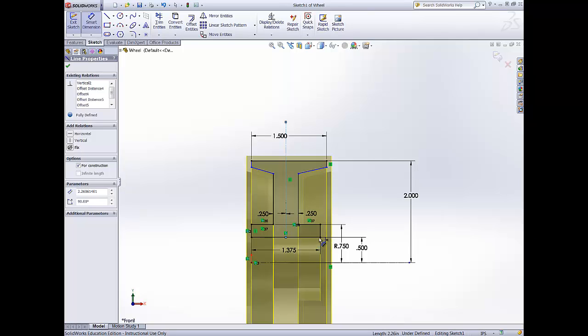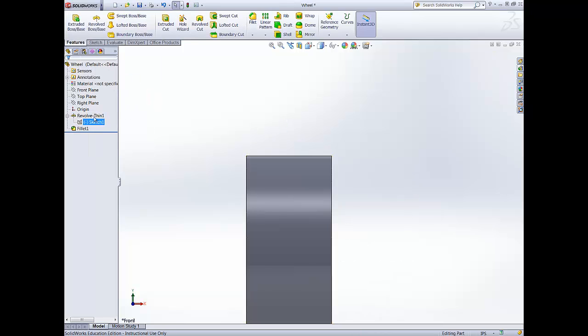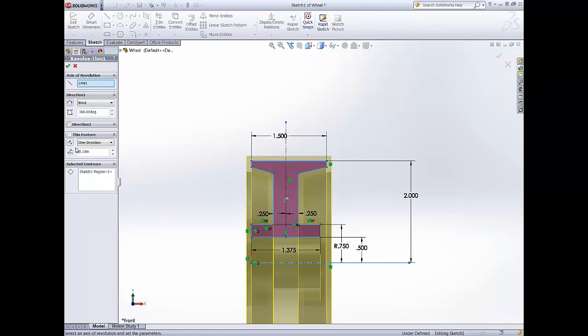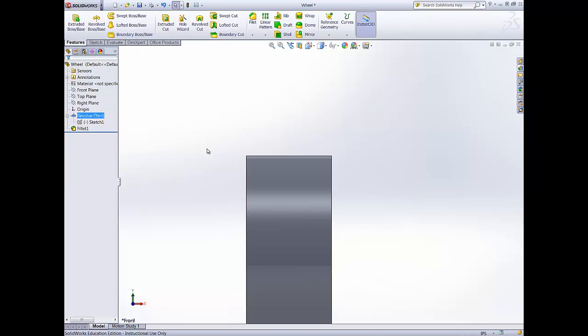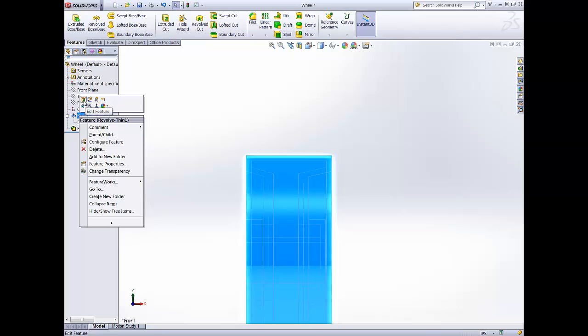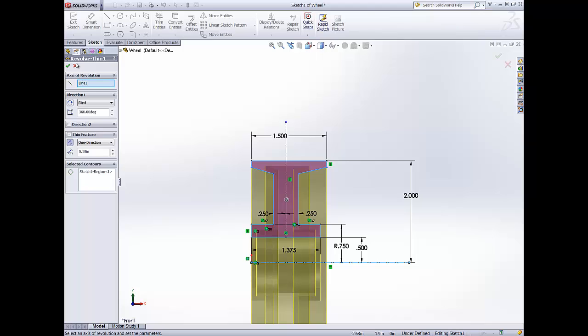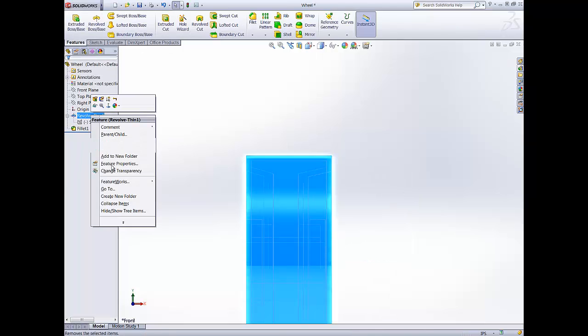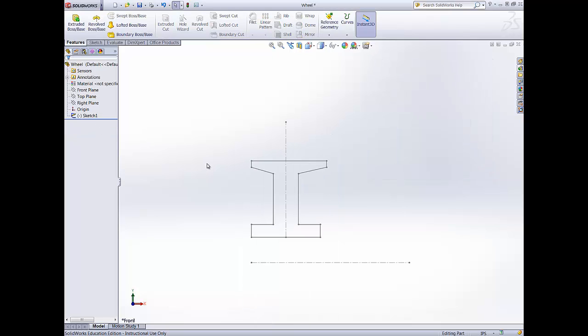And find out why we're shifting so strangely on this. Let's go look at this revolve real quick. And see we're going two directions on here at once, and we don't really want to be going two directions. So let's go in and we're going to do a fix here on this extrusion here. It's trying to revolve in more than one direction. So the easiest fix to get that out of the way is we just need to delete that whole revolve and take that out. That also takes out the fillets of the revolve.